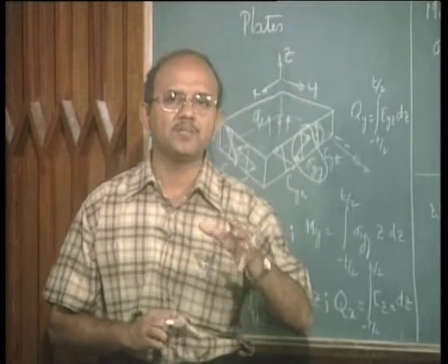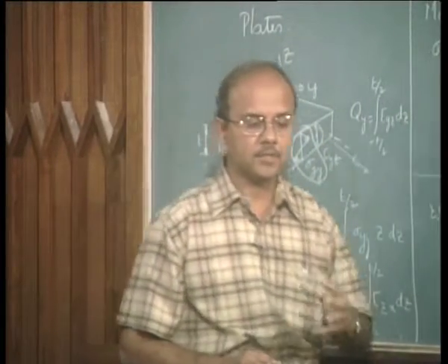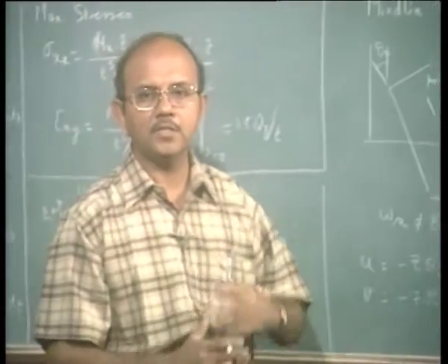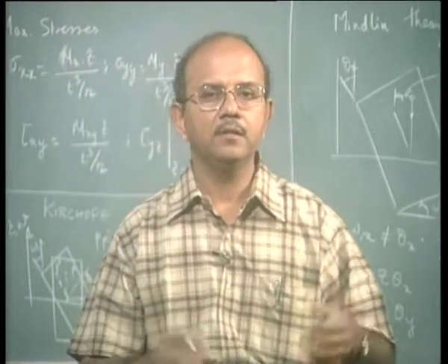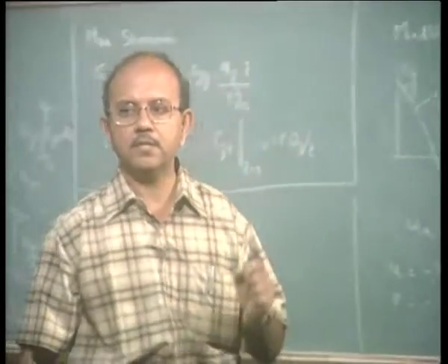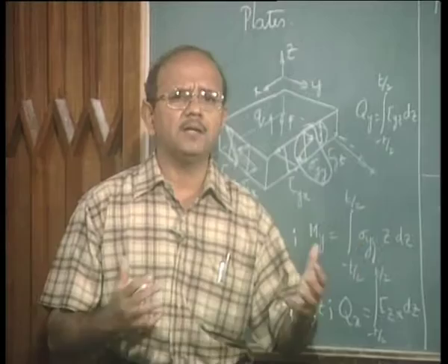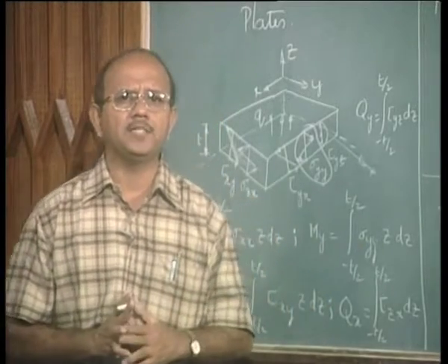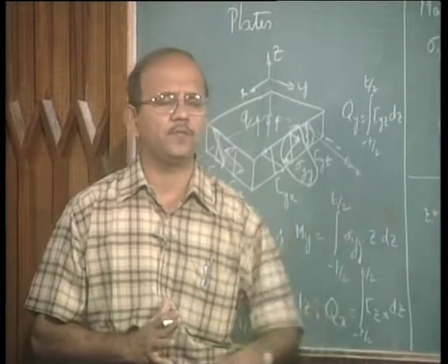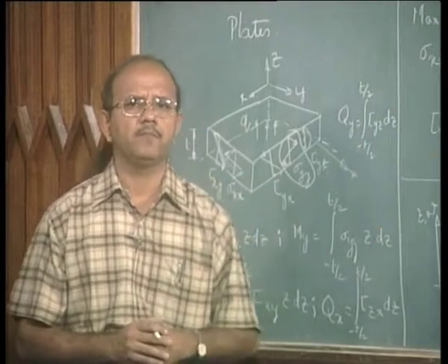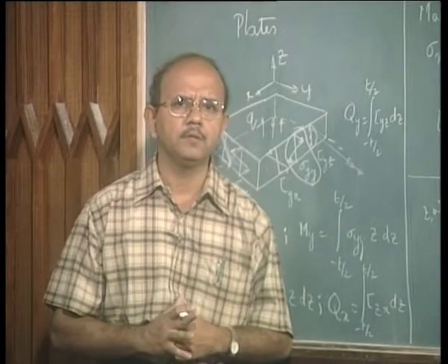So understanding plate elements helps us to understand the shell elements and apply them in certain situations. Now the plate theories can be broadly classified into what we call as Kirchhoff theory and Mindlin theory. Now what is the difference between them?